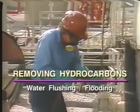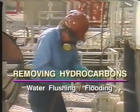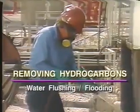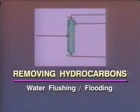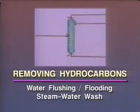Some columns are flushed out with water and the liquid containing hydrocarbons is drained out the bottom. Other towers are completely flooded with water. The flooding operation floats hydrocarbons to the top of the column where they are removed. In some instances, a combination of water and steam is used to clean out the tower.